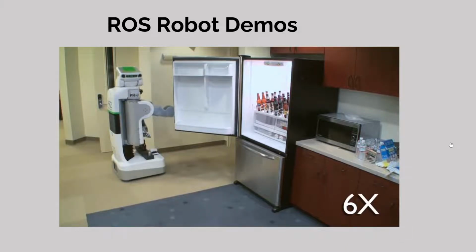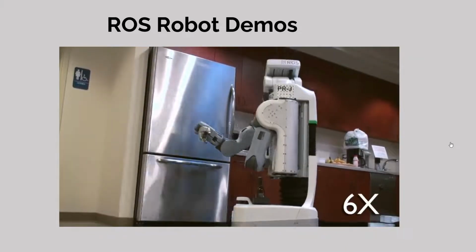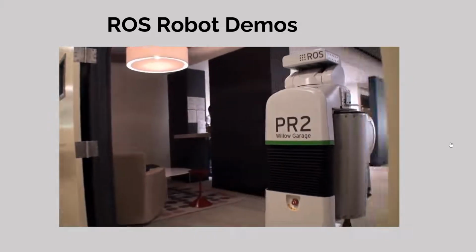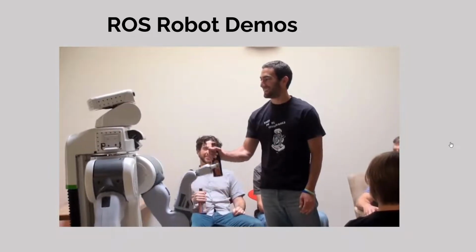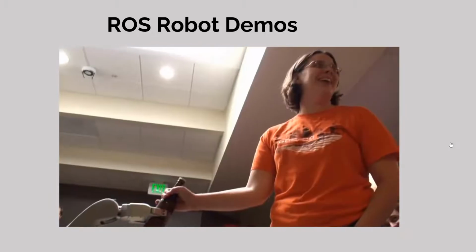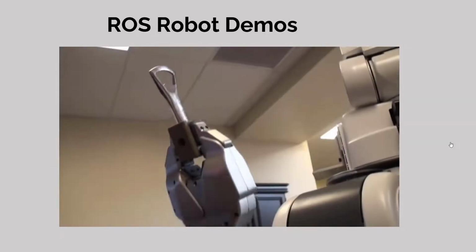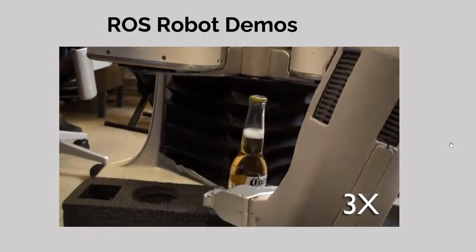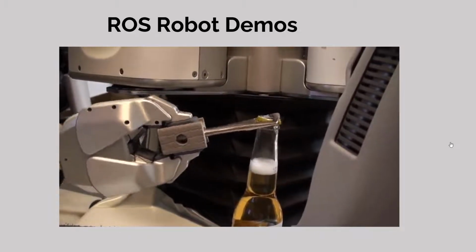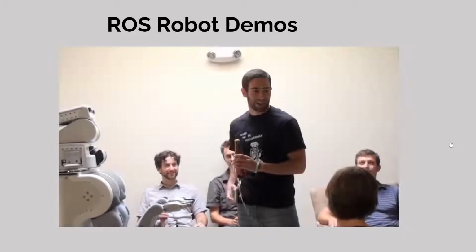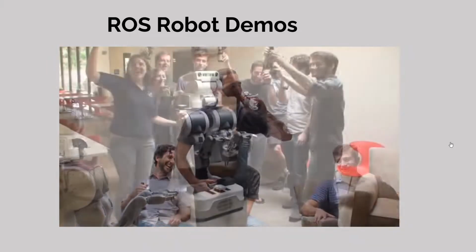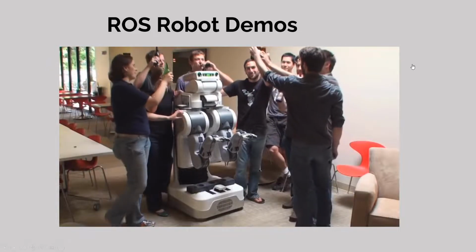Currently I'm doing a deep learning program from NVIDIA. NVIDIA has some deep learning APIs for object detection and so on. So what ROS does is take images from the camera and send them as a topic, and this detection node will subscribe to the camera images, convert them into NVIDIA CUDA format, do the detection, and then convert the detected image back into the ROS equivalent. So currently I'm working on this stack.